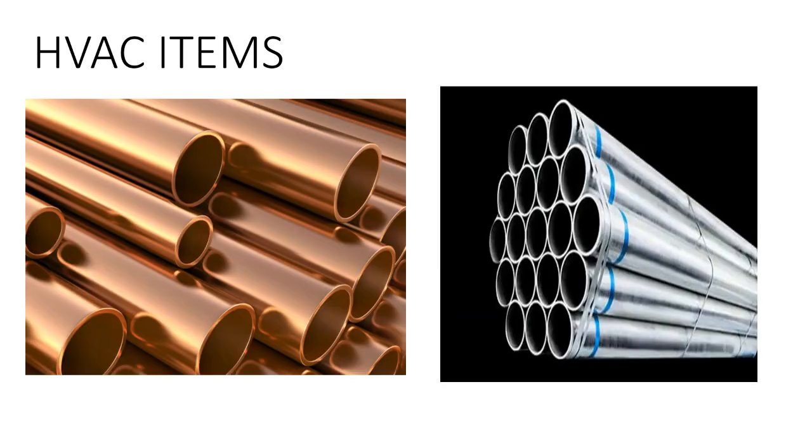Also, I forgot to explain this. When it comes to pipes, we will be insulating these pipes as well. Just as you insulate the HVAC ducts, you have to insulate the HVAC pipes too. You will be providing rubber insulation or foam insulation, depending on your project specification. If you want a cheap insulation, you can go with rubber insulation. If you want a good insulation with good thermal efficiency, you can select foam insulation, or maybe fiberglass insulation. This insulation also shall be considered.